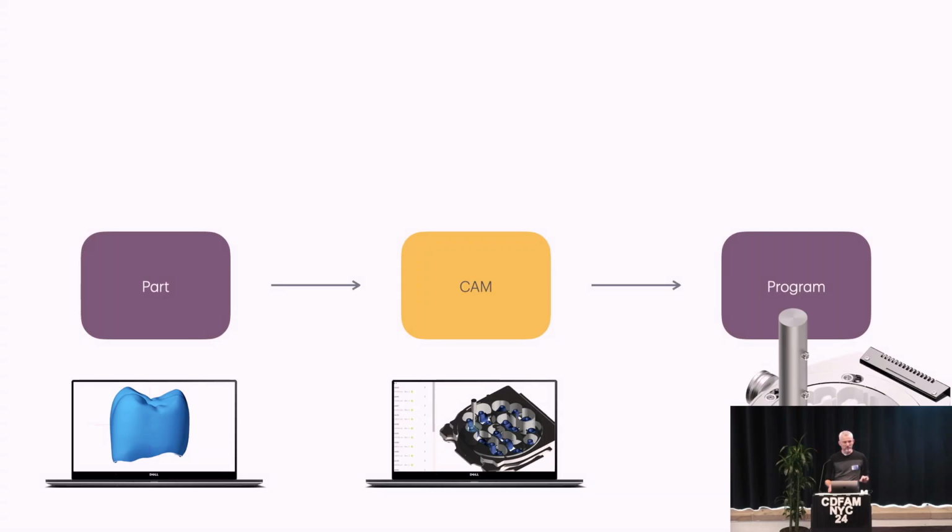Just briefly, for the designer crowd, with CAM, you have a part, then you go into a separate program that turns the geometry into a program that actually allows a machine to produce the part. Sounds very simple, but then there's a whole bunch of decisions you need to make about positioning, orientation, fixturing, nesting, process parameters, like in the CAM product.